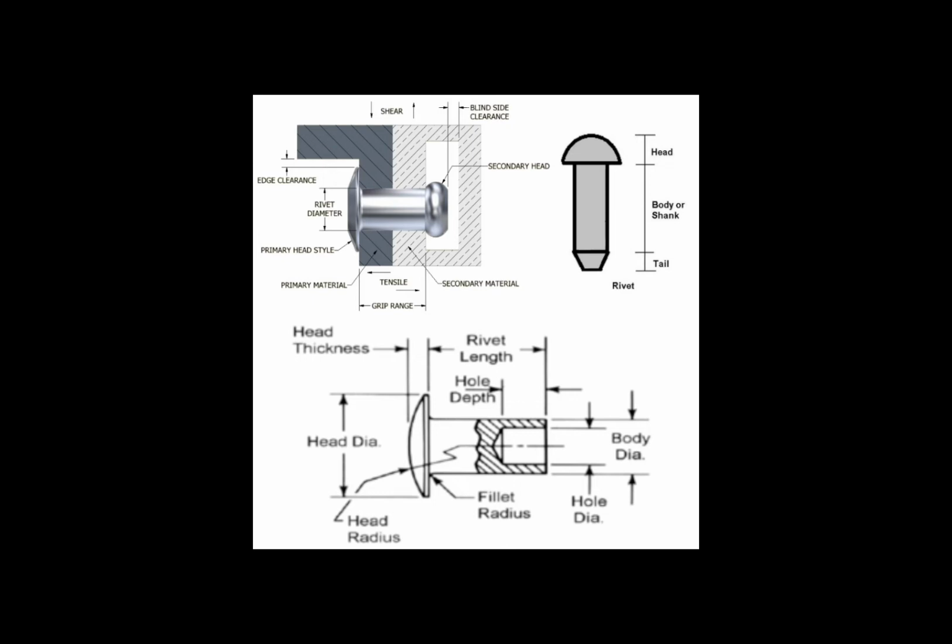What factors are used to determine setback? Radius of the bend, thickness of the material. When bending sheet metal, how should the grain be in relation to the bend? Perpendicular. What is a bend tangent line? Line at which the metal starts to bend.